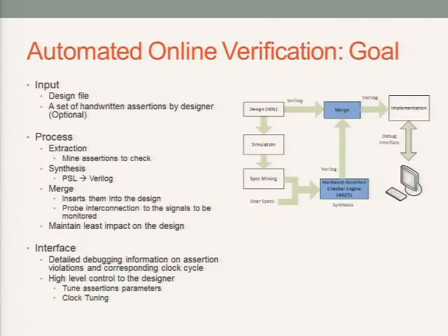So it's more like encapsulating properties and then verifying those things. Naturally, I think in your mind, everybody is going through that process, but it's more like a formal thing. I have this thing in my mind, let's go and check it. But here in assertion-based verification, you have to write things down in a formal way, using linear time logic, using conditional statements, and any kind of logic that you can write down on a piece of paper and then check, instead of running things in your mind. So it has the potential of finding bugs early in the RTL level design, and detecting them earlier than before.